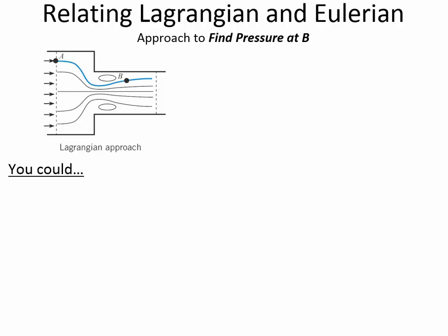That's one of the assumptions, that Bernoulli's equation will tell you the change in pressure along a streamline as long as it's an inviscid fluid, meaning that it doesn't have any viscosity. It's incompressible, and the flow is steady over time. But along a streamline is not real convenient.